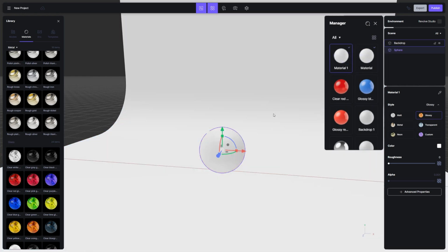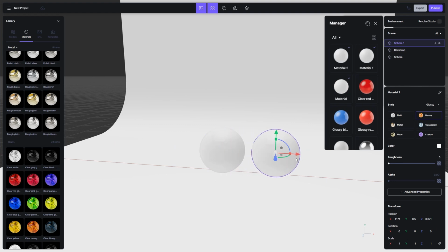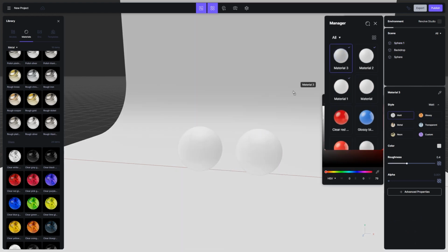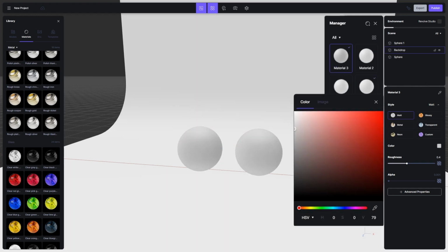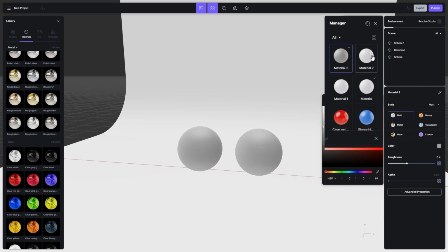When you add an object through import or copy and paste with Ctrl+C and Ctrl+V, the material will also be created. You can apply materials to multiple objects. If you change the settings, all objects with the applied material will be updated simultaneously. Right-click on the material to manage it through the menu that appears.